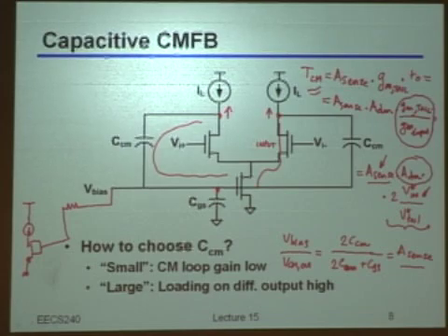So how much accuracy basically do we need? Then that is the point, right? So I don't know, how much can we tolerate? That's depending on the precise problem that you are solving. But okay, maybe with 1 volt VDD, you can kind of accept a common mode disturbance of maybe, I don't know, 10 microvolts. Is that a problem? No, that's not a problem, right? I'm just making up some numbers.